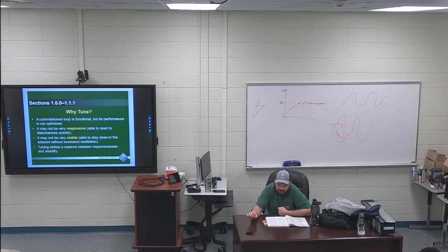Online test question. PID control is recommended in systems where the load on the process changes often and the controller is expected to compensate automatically due to frequent changes in set point, the amount of energy available, or the mass to be controlled. So when you think of PID control, think of adding derivative, it's for stuff that's changing a lot.